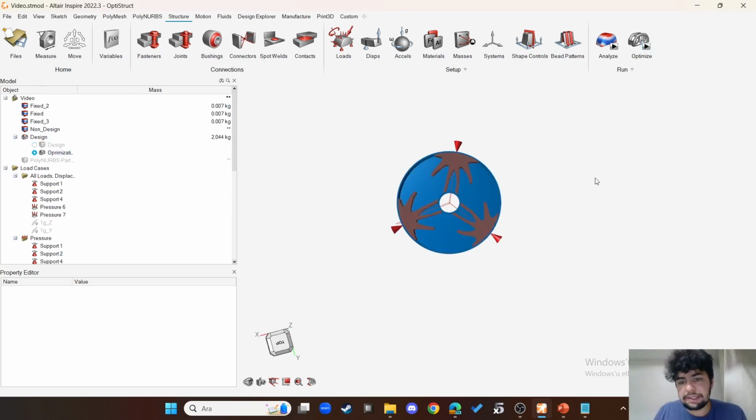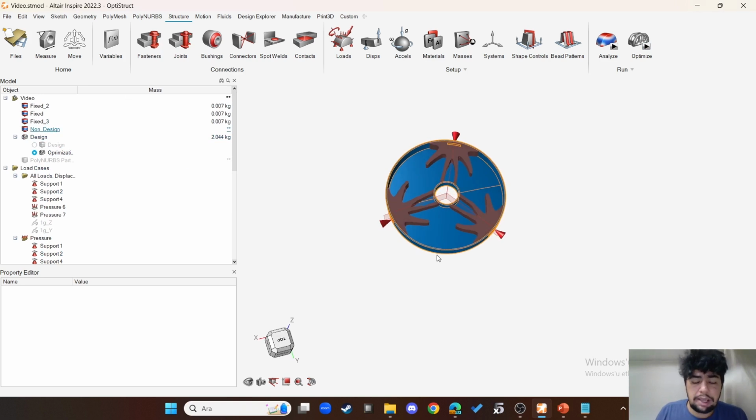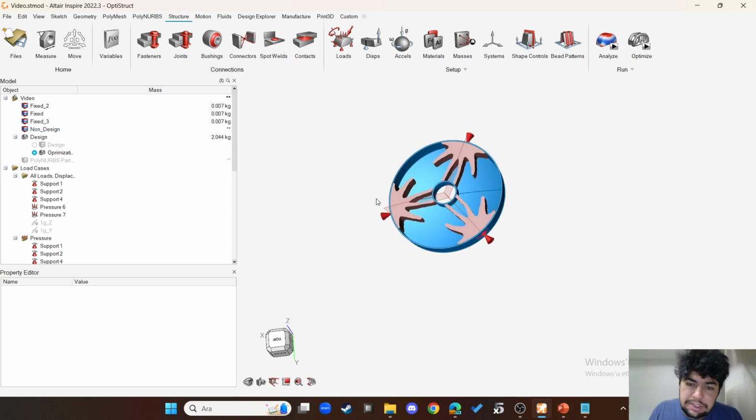So this result is logical. Why is it logical? Because especially axial gravity and polishing pressure create some moments about these constraints. If you simplify this model and think of it as a cantilever beam under distributed load, if you were to optimize that, you would expect something like thicker at the root and thinner at the edge. And it's exactly like that. We have thicker at the root and thinner at the edge structures.